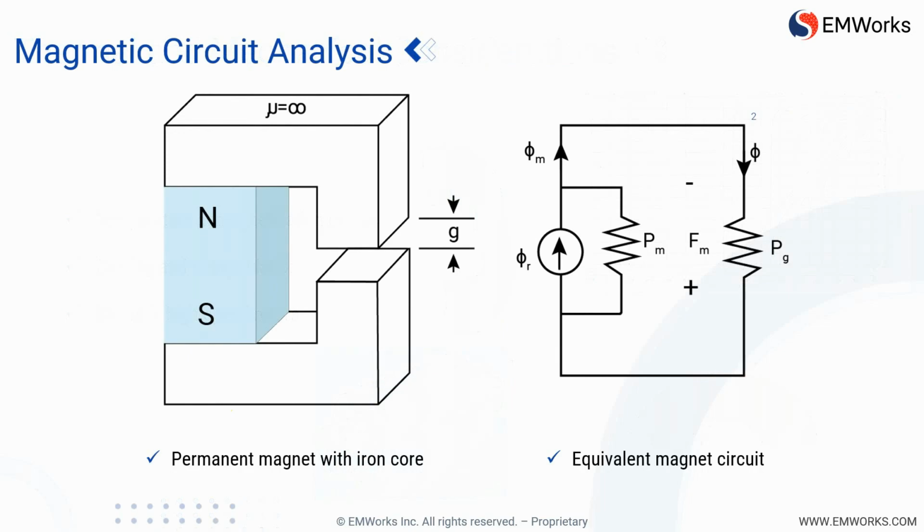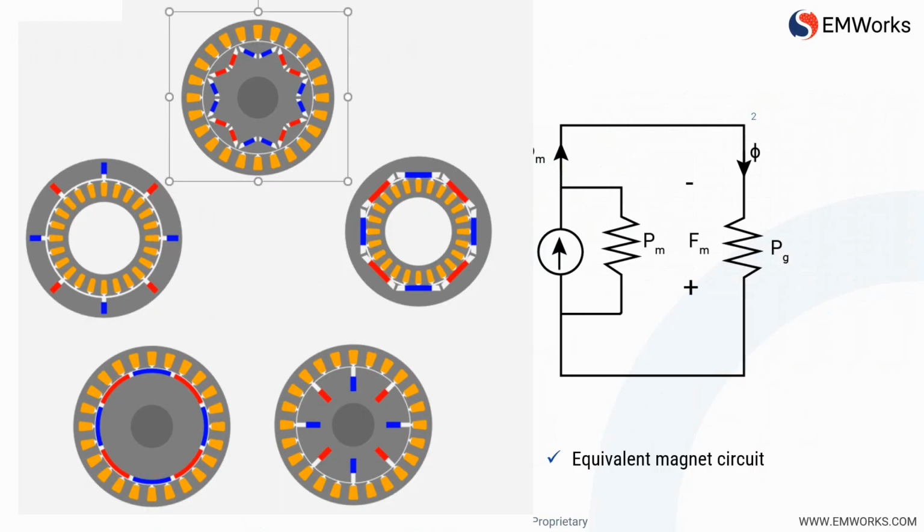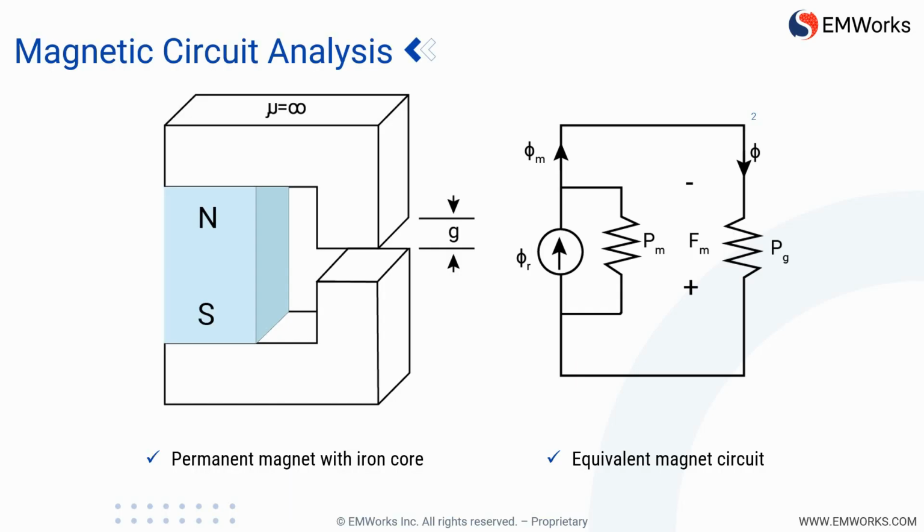Magnetic simulations must be coupled with thermal and mechanical analysis to ensure performance stability under real operating conditions. For example, a thermal rise of 50 degrees Celsius can reduce the remnant flux density of NdFeB by up to 10%. Advanced simulations also allow the designer to test different magnetic topologies, V-shape, spoke, inset, and compare their performance metrics under varying load conditions. Through parametric sweeps, optimization algorithms can fine-tune magnetic dimensions, air gap length, and stator slot design for maximum system efficiency.